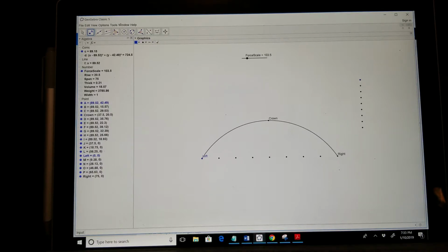So I'm going to change the icon in the point to make it a big red X so that I don't make a mistake. And that's a nice little trick here. So now I'm finding the centroids of these points by going back to the midpoint here. And there's my big red X. So it's unambiguous. I know exactly that that's where the load is going to go. And then I'll draw the vertical lines through these red X's and through the right also, because my funicular is going to end there, and then we'll stop and we'll do part 2 of the video then.